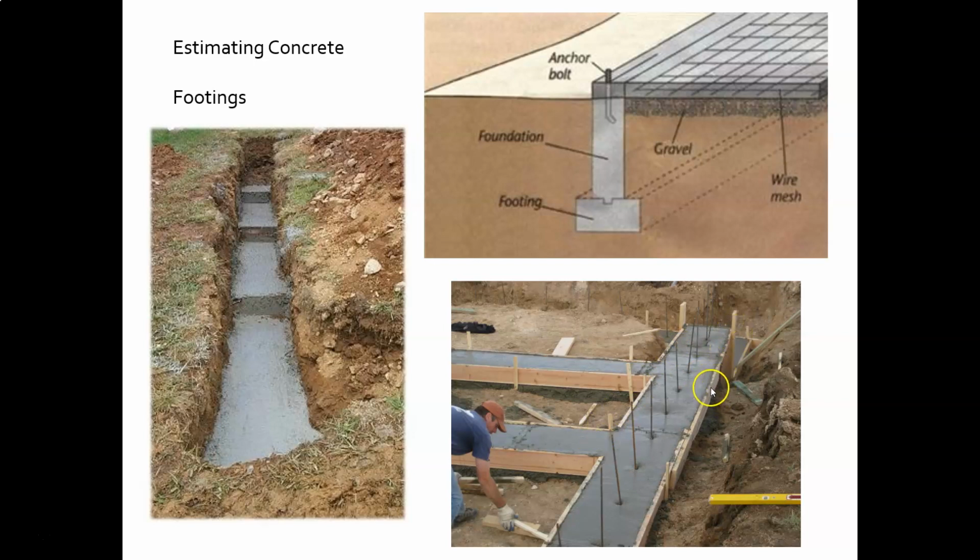So we're going to have to do some math and move this dimension. Whatever this footing is, if it's, I don't know, 50 feet to here, and if this is 2 feet wide, we're going to have to take that 50 feet and back up 2 feet and call it 48. So the linear feet of this run is 48, because we don't want to double count that. So that's a lot of maneuvering with the dimensions.